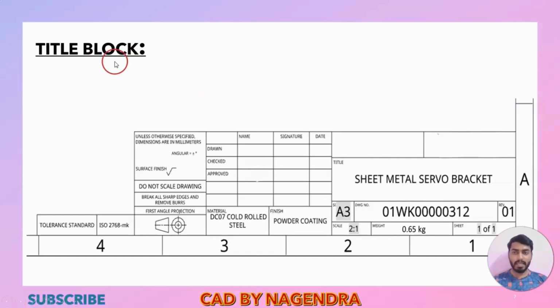It means in the title block we will have the part name, as we can see, the title, the part number or drawing number, the sheet size we need to take, the scale ratio, the finishing symbol, the material we need to use to manufacture that particular part, and the angle of projection with reference to which we need to read that engineering drawing. The entire detail about a particular drawing sheet will be specified in this title block.